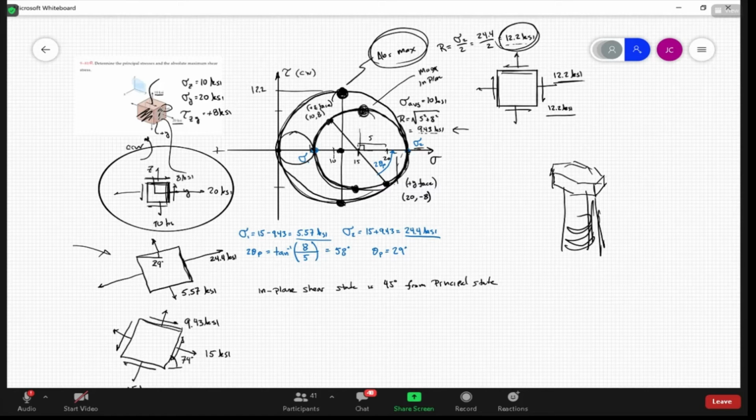And then they put a wrench on here, out at a distance, that puts a force. So we have one of those classic combined loading problems. So as we did in chapter 8, you get a planar state of stress here, right? Maybe it looks like this, right? And then from this, you can do Mohr's circle and figure out the principal values and the principal orientation, okay?